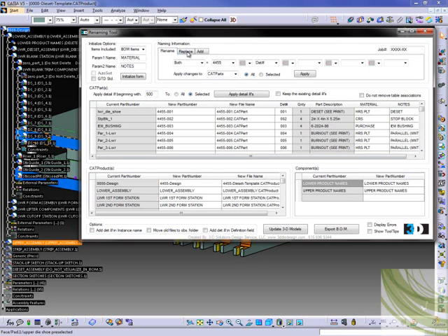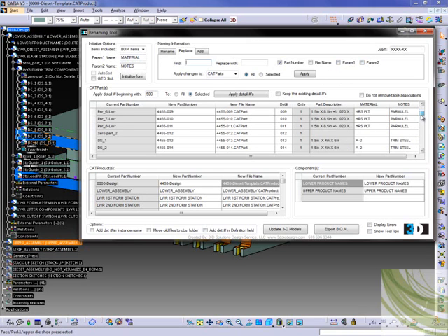any of these components. If we were going to do replacing, we come in here and we can find a particular string and replace it with another string, and you have the option to do that in part number, file name, and you also have param1 and param2 here. This is really nice because if you have, say, a material change and they want to go from A2 for all the trim steels to S7, we can select that param1, which is material, and we can change all these features that are A2 currently to S7.